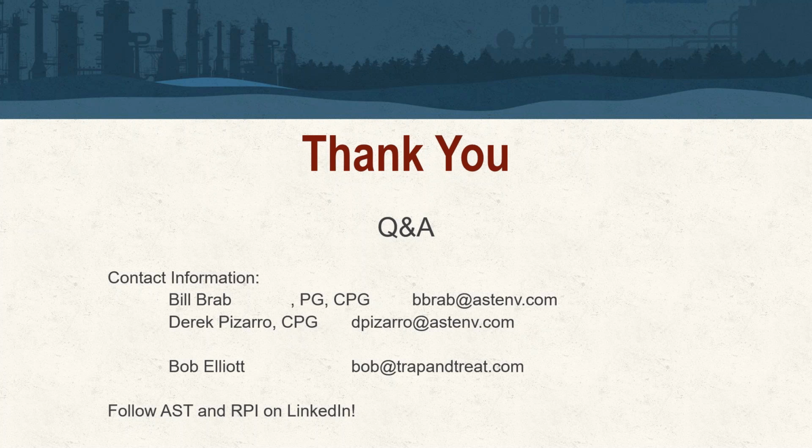What is a heat pulse flow meter? I saw that included on one of your diagrams. Yeah, it's a great question. A heat pulse flow meter is one of the additional tools that can be utilized in a downhole geophysical study. Essentially, you can think of it as using a packer to isolate a specified interval within a borehole to see if there is any sort of fluid migration through that specific interval.